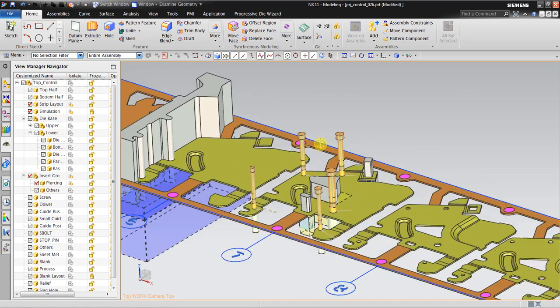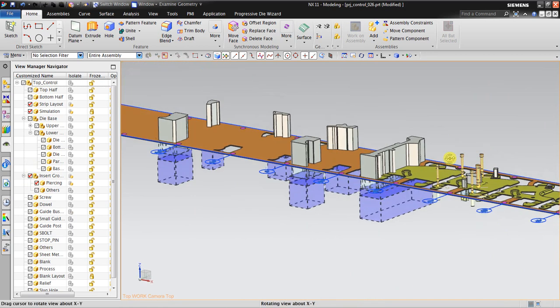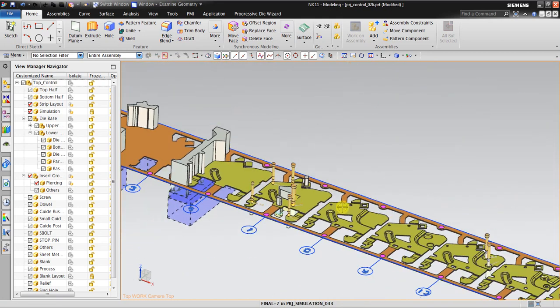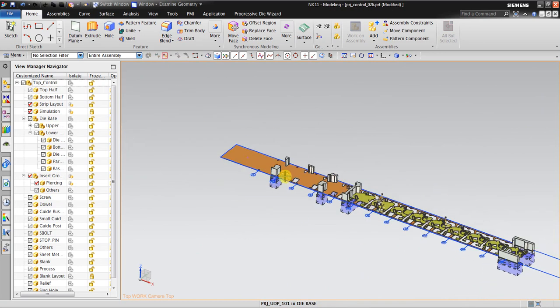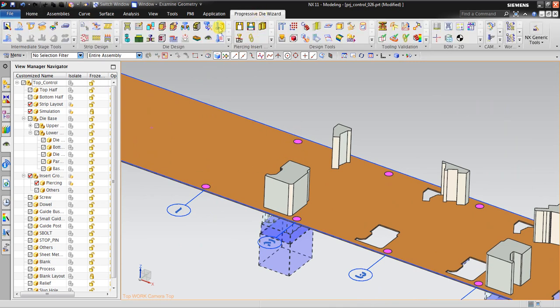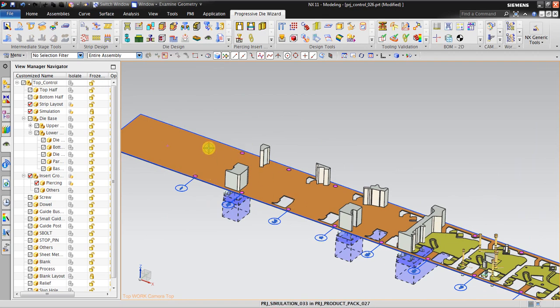Here the user define piercing. This is also the user define special piercing. This is the trimming, but for the pilot hole I will not use a piercing tool, I will use this one, standard parts. So it's different. On the next stage I will explain how to create the pilot hole, the pilot lifter, and everything related to this pilot hole.